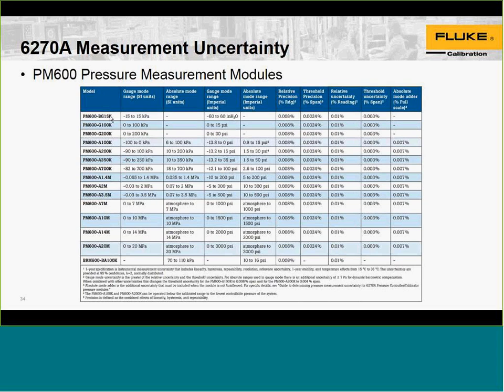So other than the complication of calibrating in a different fluid versus the operating fluid, which is usually taken care of by the calibration house, or if it's being sent to calibration for service, there shouldn't be a big effect on the performance. Just make sure that head correction is appropriately accounted for.